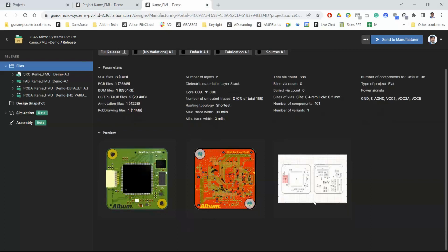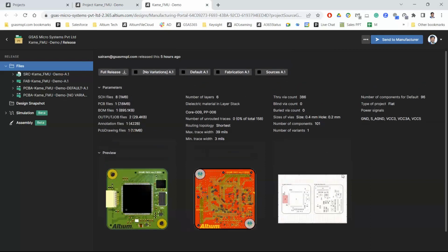design information and the preview. If you have shared a Gerber with your fabricator, and, as you have explained in a case, if he found some clearance issue and adjusts the Gerber, once he makes any adjustments he has to take prior approval from the designer. Once he sends the Gerber back to you, how can we compare that Gerber with the existing Gerber?